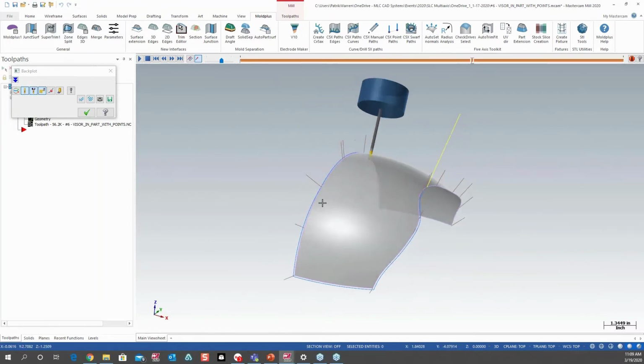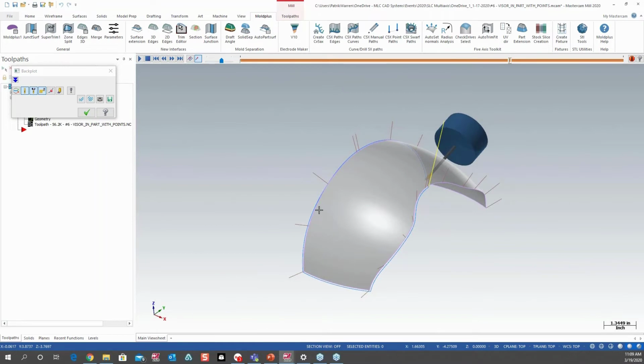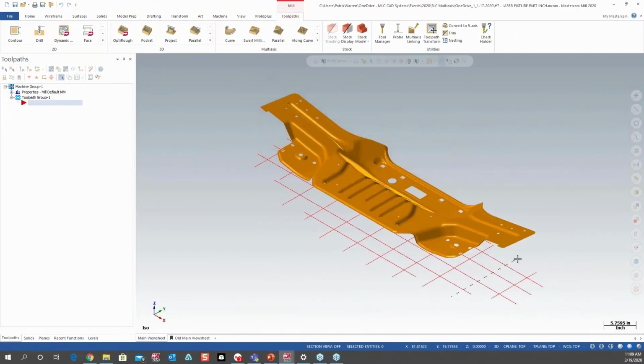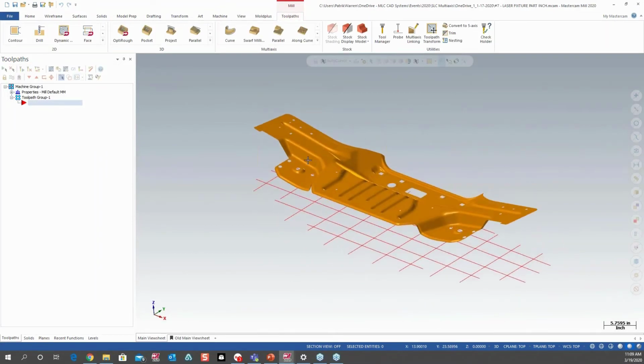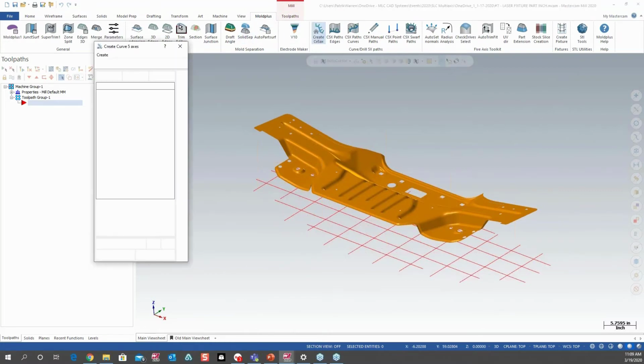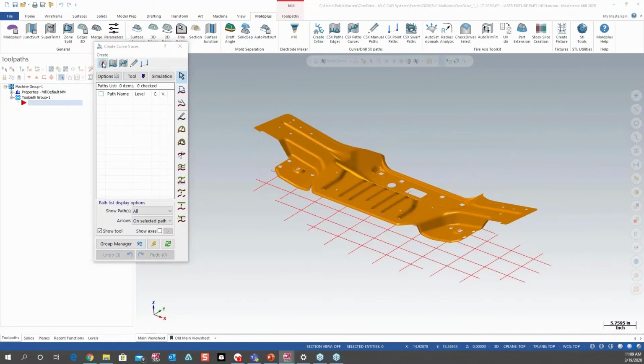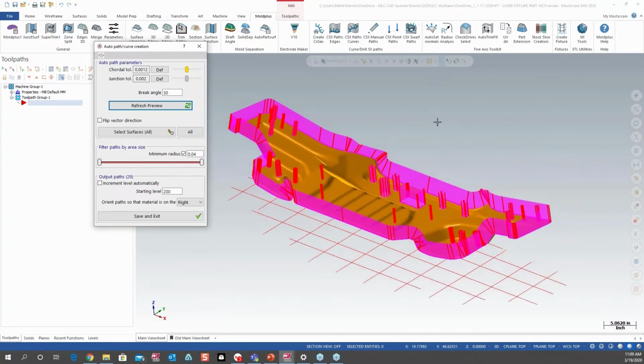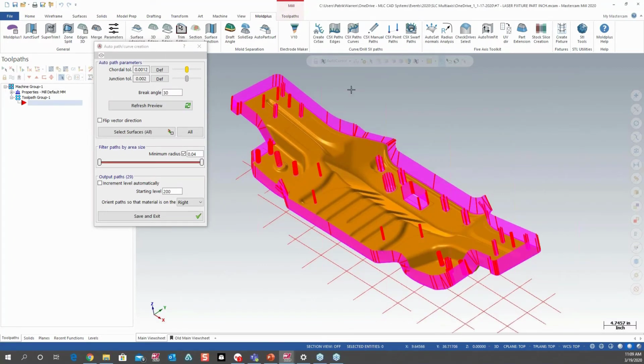I'm going to pull up this last example of Moldplus here. I'll show you the 5-axis toolkit on this as well, or the 5-axis curve. So if we jump into here, create a curve, do it automatically. Now there's a bunch of internal positions on there as well, and it picked them all up. So if I just change my filtering, dragging from the left side, which is my small side, I can tell it to ignore anything that I don't want it to.